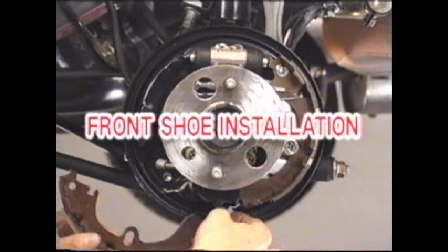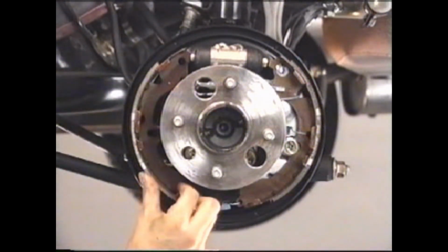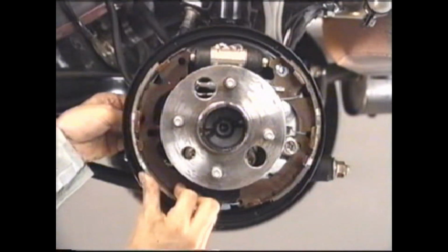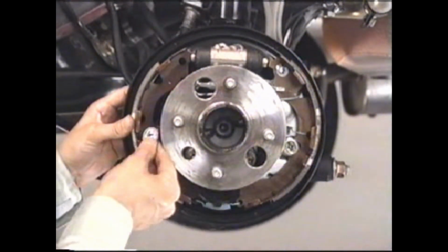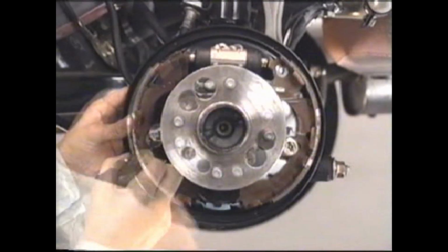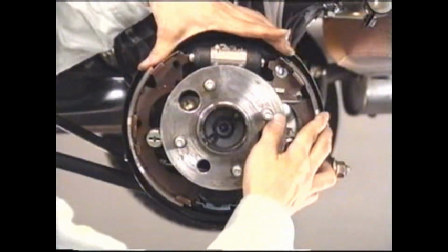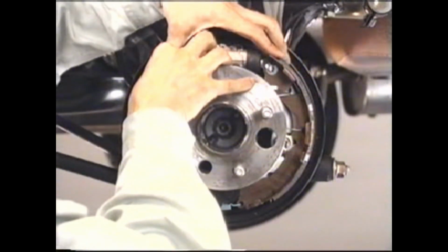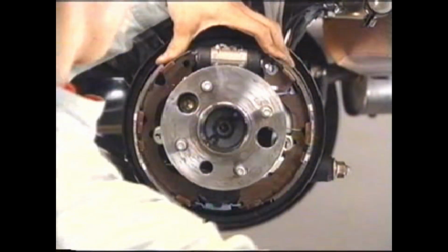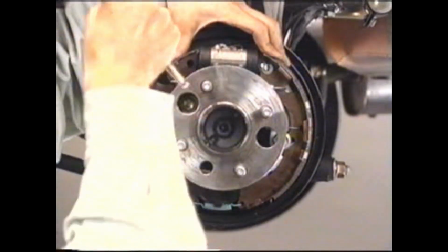Next, install the front shoe. First, assemble the anchor spring between the front and rear shoe. Follow the same procedures as the rear shoe and set one side of the front shoe to the wheel cylinder and the other to the adjuster. Assemble the shoe hold-down spring, 2 retainers, and the pin using the SST. Connect the return spring using the SST.